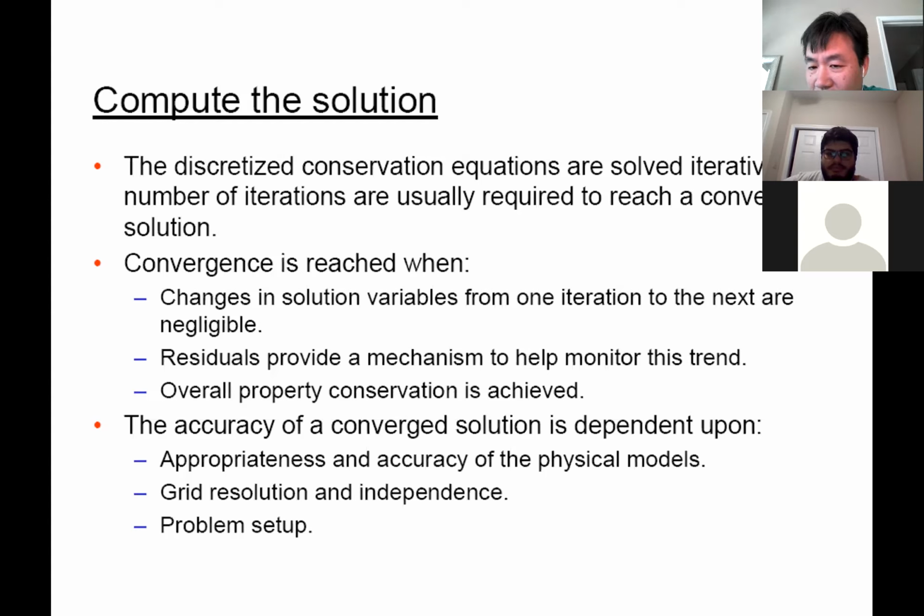For anybody doing CFD, you need to remember this. You determine the grid size. There's no almighty method to determine what the grid size is. Every problem you simulate is different. It requires a finer or coarser mesh for every problem.